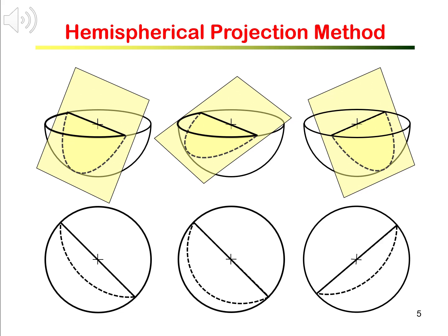When a plane has a steep dip angle, the projection is an arc closer to the diametrical line. For a plane of gentle dip angle, the projection is an arc closer to the circumference. This is shown by the left and the middle projection diagrams.